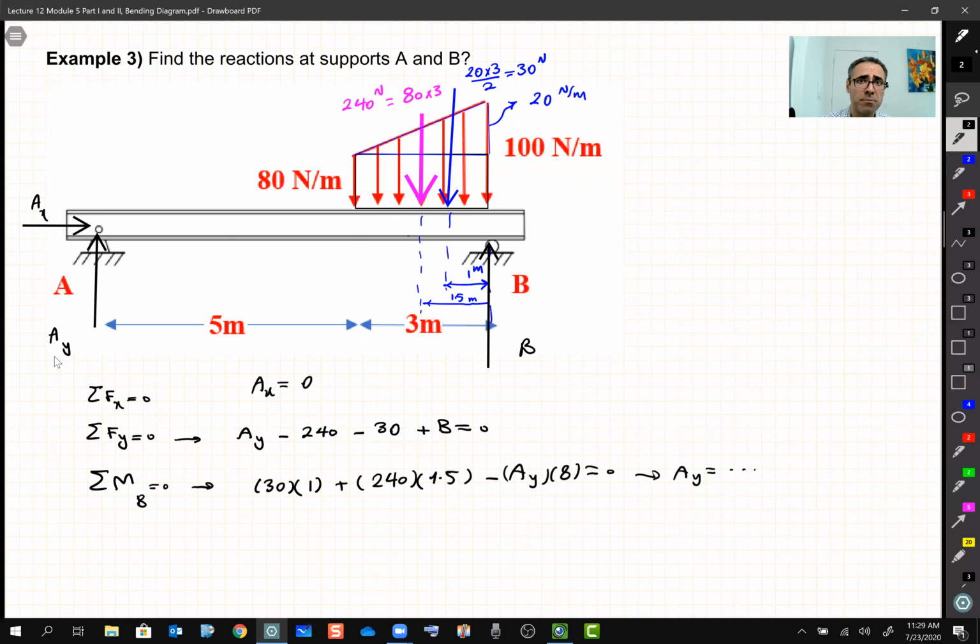When we saw distributed load, simply we find its equivalent, which you saw in this course. We just deal with 2 types of load. One is uniform, a rectangular shape, and then another one is a linear load, which is a triangular shape. The most difficult one is going to be something like this one, which you break down into 2 shapes, as you see here. And after that, it's just the equilibrium equation, which we deal with.